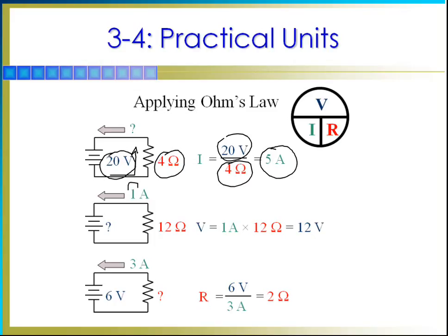In the pure form, if you know what your current flow is or what current flow you're going to require, and you know what your load is or your resistance, well, current times resistance, 1 amp times 12 ohms, your voltage source will have to be able to handle 12 volts.